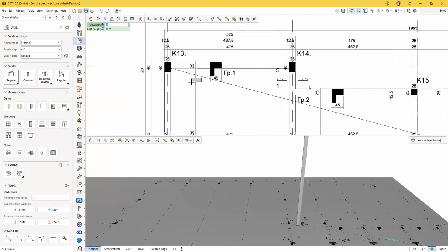Now we do have that default thickness set. And when I'm looking at my wall here that's on my cursor versus this wall that's here in my CAD plan, I can see that this is a much thicker wall. I will be able to use my stretch nodes on my wall once I get it placed to make it the exact correct size to match my CAD plan. When we get to our exercise, I'm going to have you guys just put walls in at whatever thickness you have set for your wall schemes. Okay.